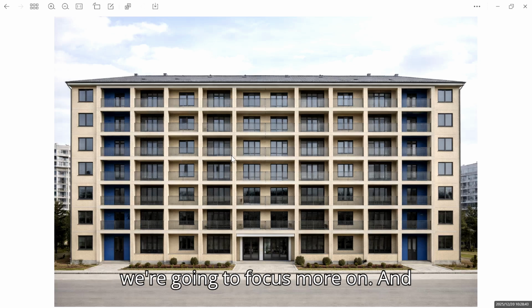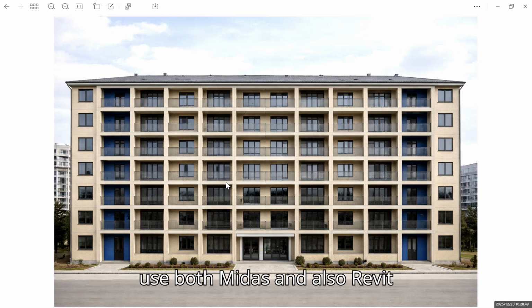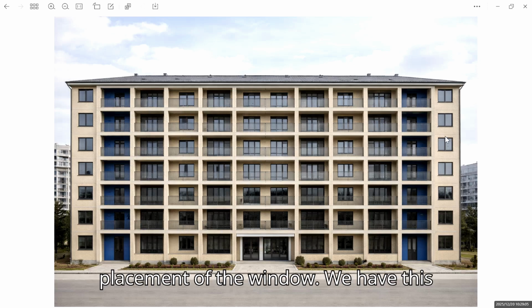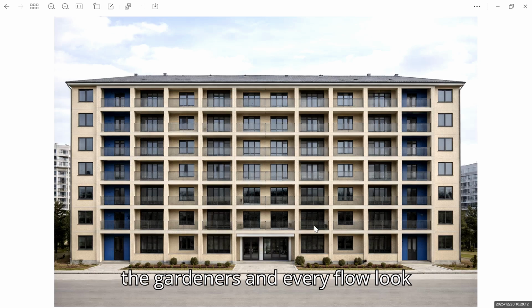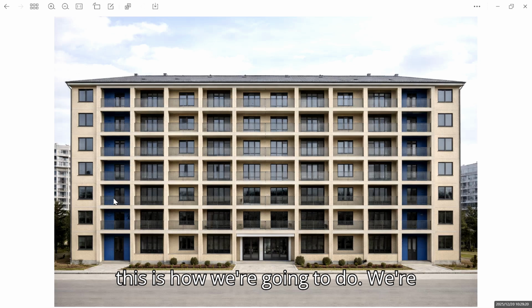So in today's video, we're gonna focus more on reinforced concrete design, and we're gonna use both Midas and also Revit software just to design this house, right? And as you can see, this house is like a concrete house using concrete material, and then it has a specific placement of the window. We have the shear wall here for the elevator and also for the staircases. We also have the girders, and every floor looks identical, all right, except the ground floor, and we have the roof top here.